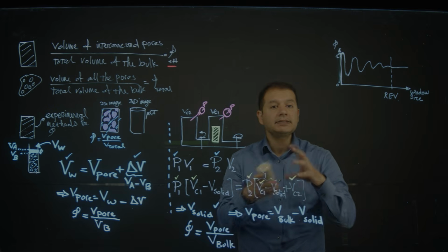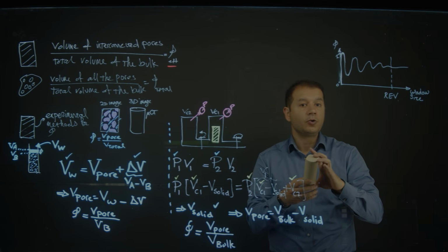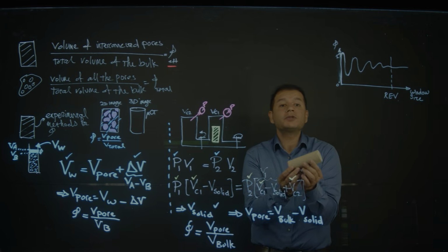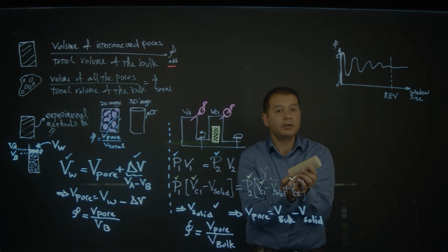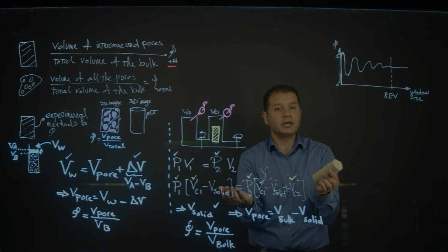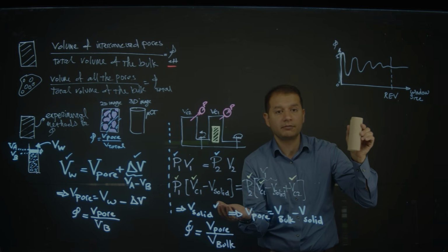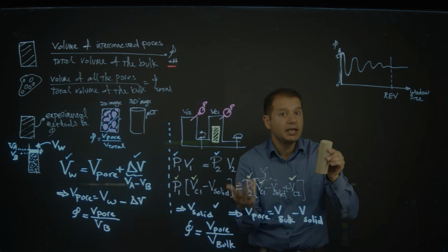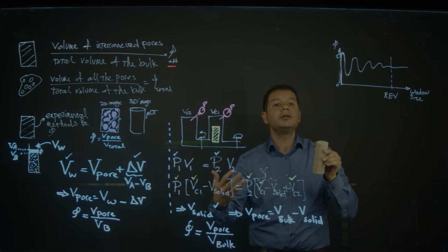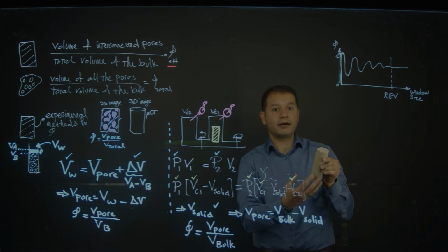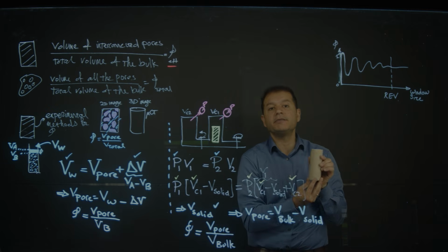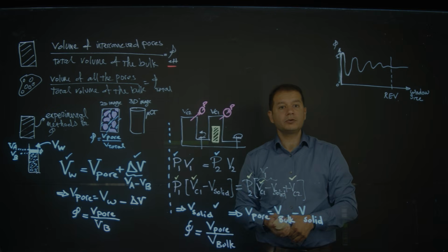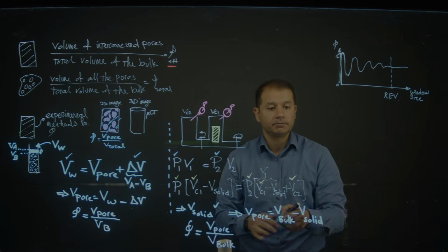So if you know the density and the mass of this system, you should know what the volume would have been if it was 100% grain, only solid. And now you know that the actual volume is bigger than that volume. Why? Because those are empty spaces. And so it gives you the understanding of the void volume, the pore volume that you have in this rock. So density and measuring the weight of it can also be used for understanding the porosity.